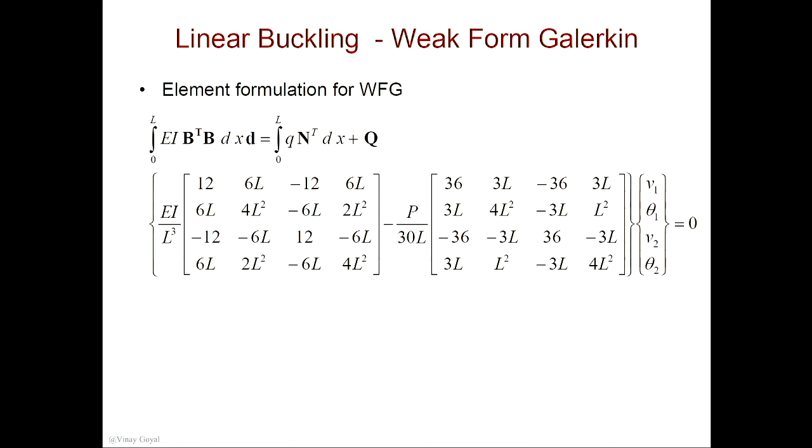Zeros. So the linear buckling solution is about that zero state, right? The nonlinear analysis, on the other hand, is not linearizing the equations. It's using the full nonlinear geometry, the large strains, the large rotations. And now what we're trying to do is use a nonlinear analysis, determining when the structure collapses.